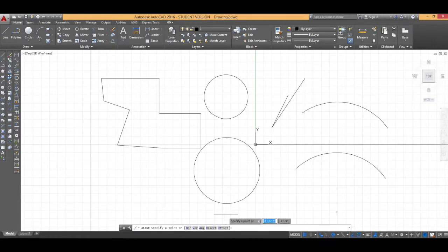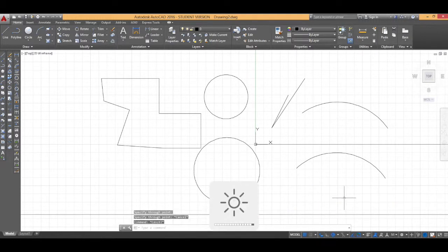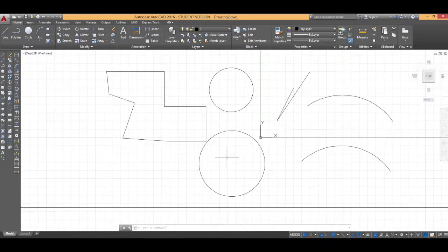Construction lines allow us to select a base point and then a direction, which will create a continuous line in whatever direction we select. This can be extremely helpful when you need to translate geometry from one point to another. We'll use this primarily when we do our elevations.